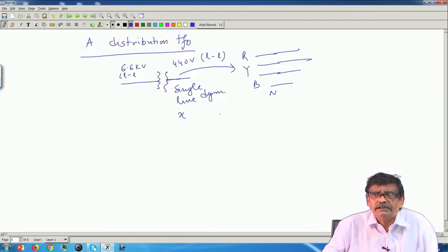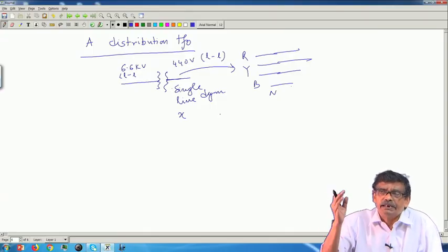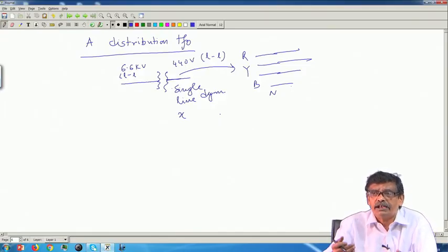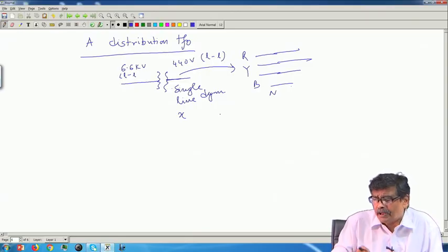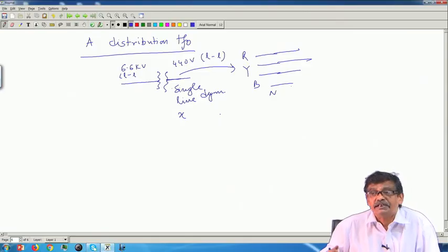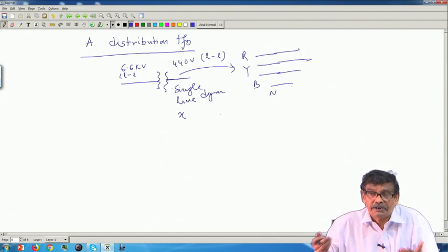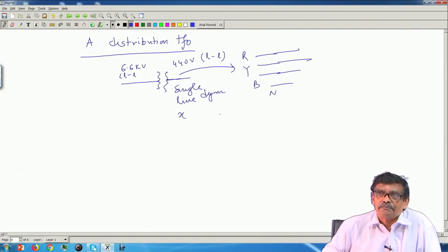Sometimes it is very light load condition, almost no load, sometimes full load, evening peak and so on, but at some other time it is medium degree of loading, maybe x equal to 0.3, 0.4, the transformer will be operating. Therefore, asking for efficiency to occur maximum at x equal to 1, that is at full load condition, will not be a very judicious demand at the time of ordering the transformer. Maybe x equal to 0.6 will be a good thing.